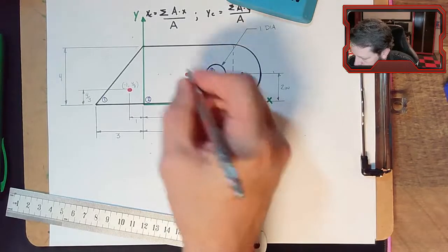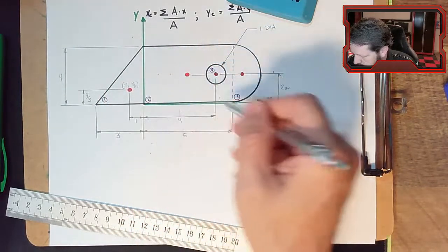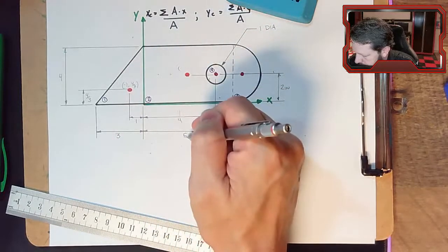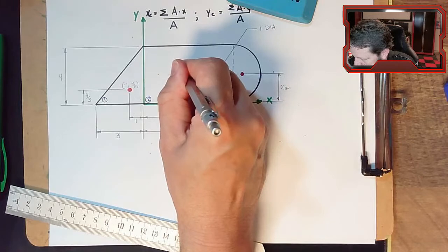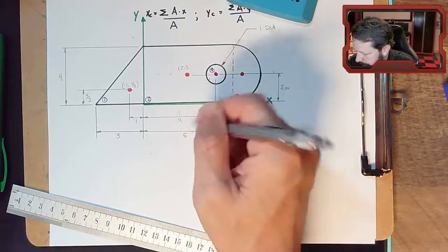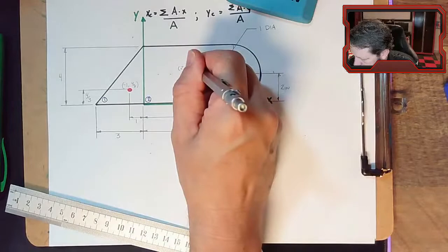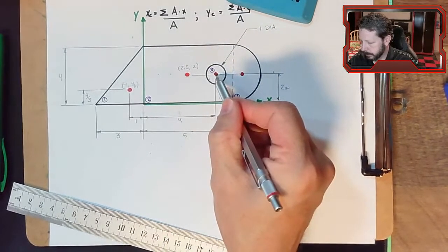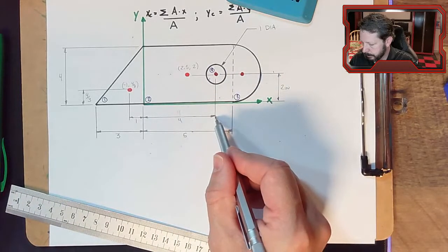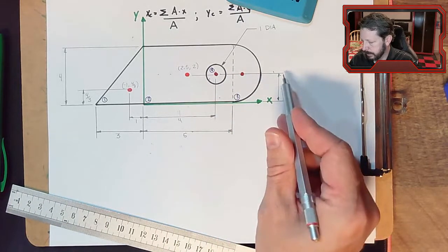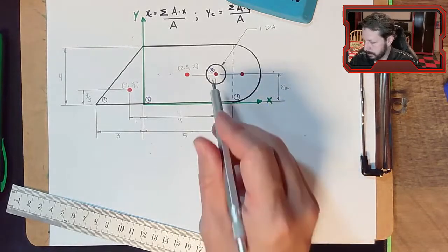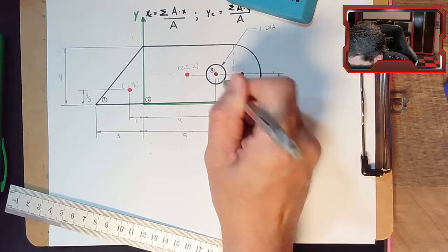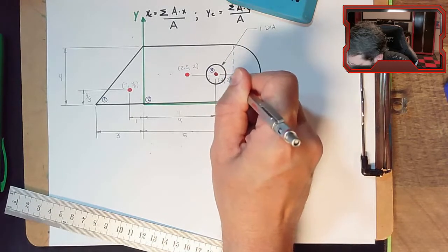This guy, another way you could do it, I suppose, if you take this same approach and not drawing lines on it, you could say, well, this is the centroid of the rectangle. The rectangle has a base of 5, so I know the centroid, without even looking, is 2.5, right in the middle of that. And then it had a height of 2. So we could label them that way. This one's already labeled, right? See, there's a 4 setting it over from the y-axis, and a 2 setting it up from the x-axis. So it already has coordinates, they're just over here. So it would be x of 4, y of 2.